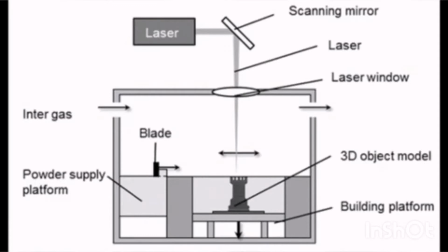put metal powder into the supply platform. After that, the device will set the scanning speed, the laser scanning interval, and hatch angle. And after that, nitrogen gas or argon gas will be introduced into the device. After the appropriate volume of gas is loaded, an amount of metal powder suitable for one layer is deposited onto the base plate using a blade.